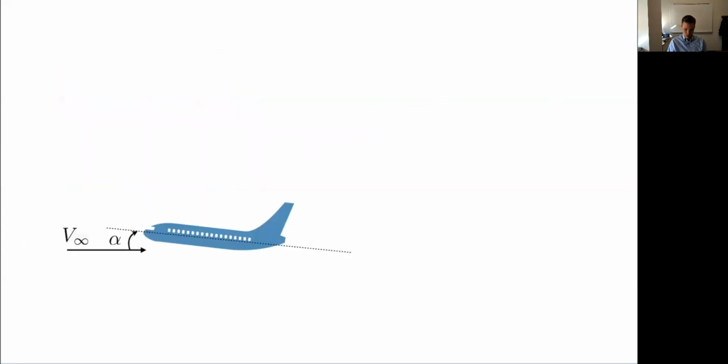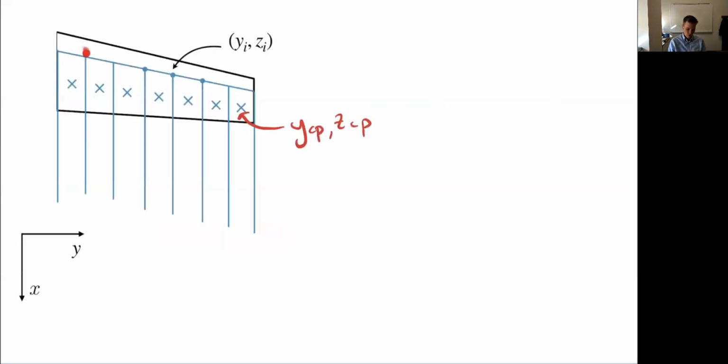All right, so as we've discussed, well, actually I have the model already. I basically just need to define a boundary condition. So I've got a model, which is I'm going to put in circulation, and as we've seen from our Helmholtz vortex rules, if this has some circulation strength gamma 1, that's going to be continued all the way along this horseshoe vortex. The next one is going to have its own strength gamma 2, which continues along its own one, and you can see these two vortices are going to partially cancel. So that's my model, and I need to decide what is the right strength for each gamma. Each panel is going to have its own circulation strength.